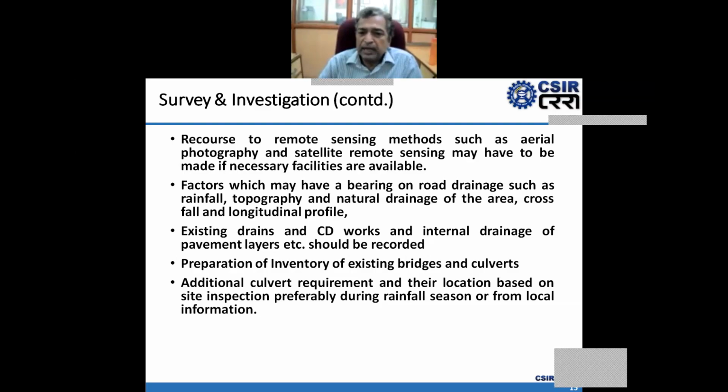Factors which may have a bearing on road drainage such as rainfall, topography, and natural drainage of the area, crossfall or longitudinal profile, existing drains and cross drainage works, and the internal drainage of the pavement layers should be recorded.